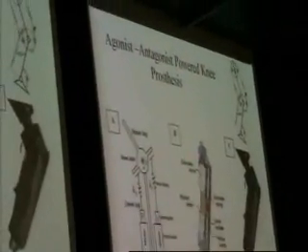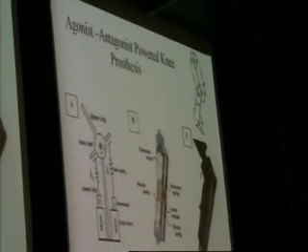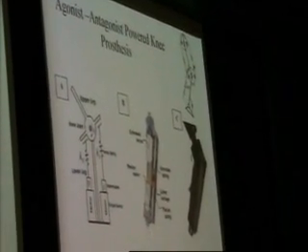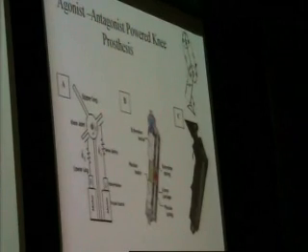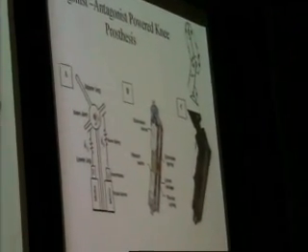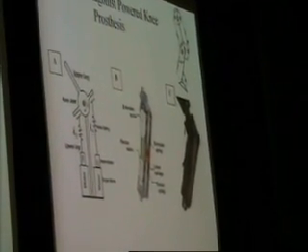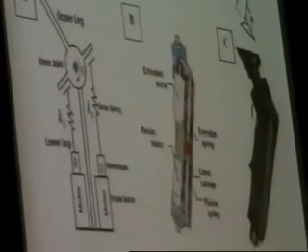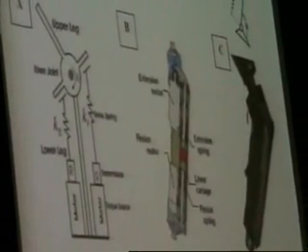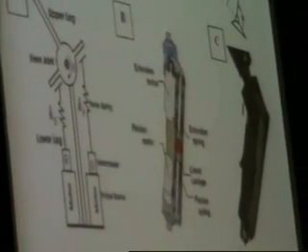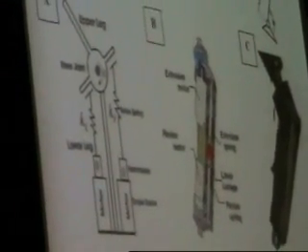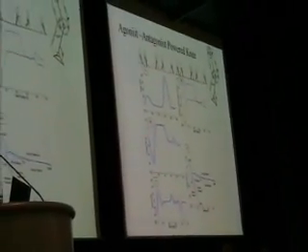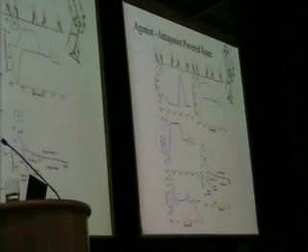In terms of a knee system, again, using models of the human leg, we're designing new artificial knee joints that exploit tendon-like elasticity. This type of actuator system has two motors and two series springs, so it's an agonist-antagonist muscle-like arrangement. We're able to capture the dynamics of the human knee in level ground walking at very, very low